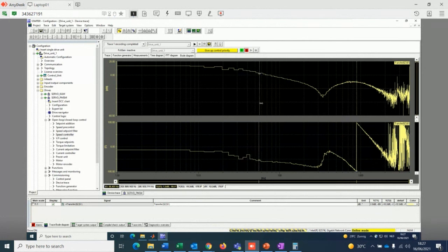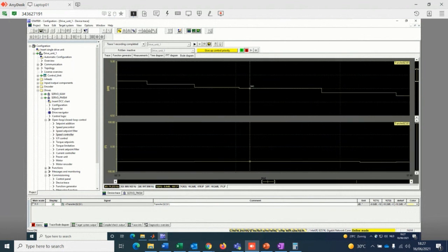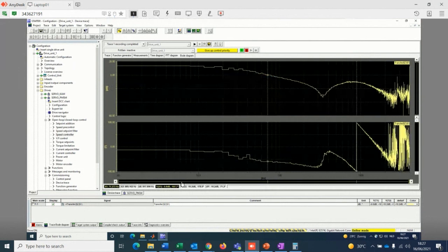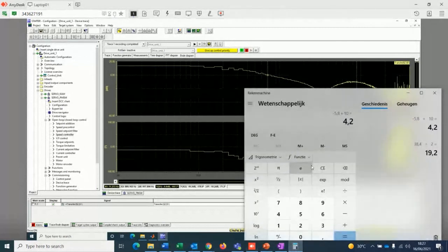Then we will measure our phase margin. So we will go to the point in which we have 0 decibels. Actually, here by luck we have the exact point. In case you can't find the exact point due to interpolation or the sampling, just go to the nearest lower value. But here we are okay because we found 0.0. Our phase at that point is minus 107.7.